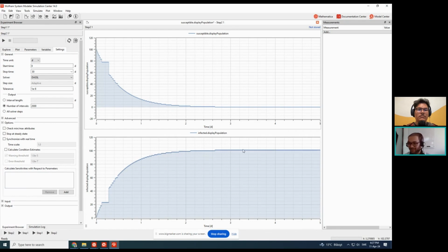and then you could see that I have a weird looking plot like this. That is because maybe my variable step solver was not good enough, or it missed some of the transition points. One way to solve it probably would be to try a different solver.